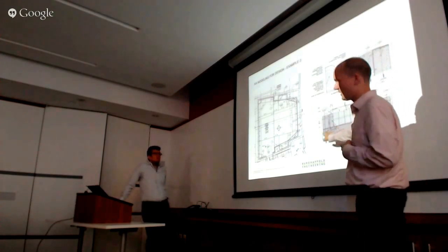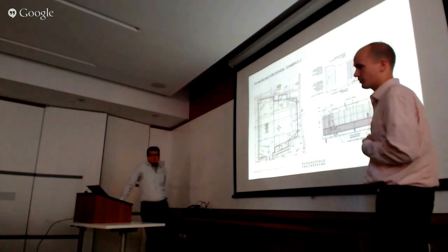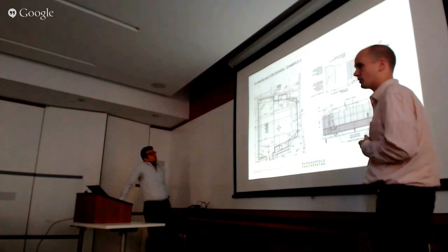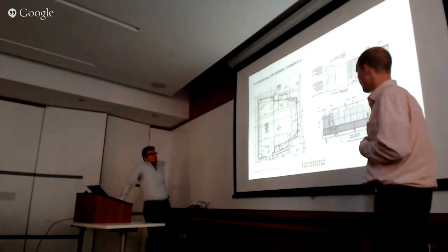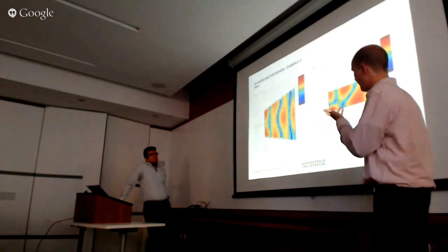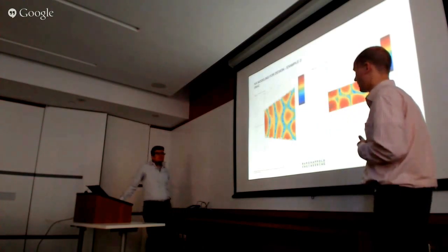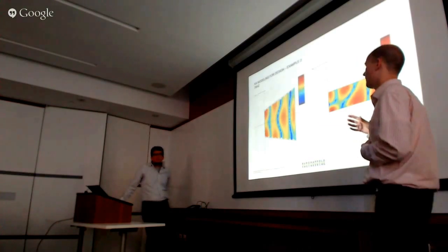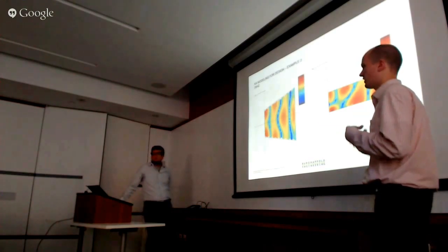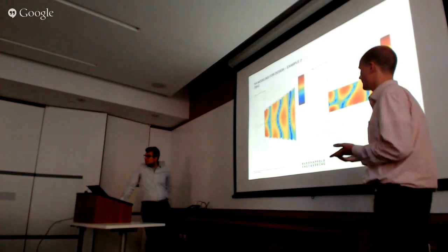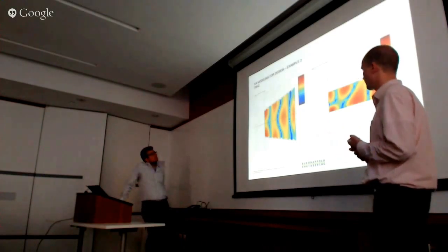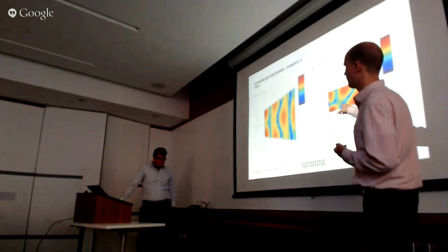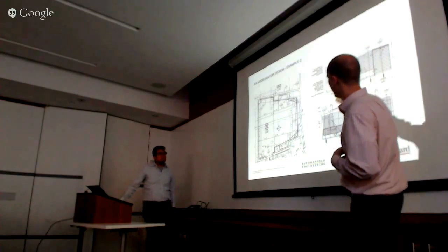And what we have along the bottom here are tuned bass absorbers, which are specifically tuned to the kind of frequency ranges that we were concerned about. So by having these models available, we're able to understand where the pressure is going to tend to build up the most. After we'd identified those locations, we're able to tune bass absorbers that are going to specifically target those frequencies in locations where they're going to be problematic. If we flip back before also as well.